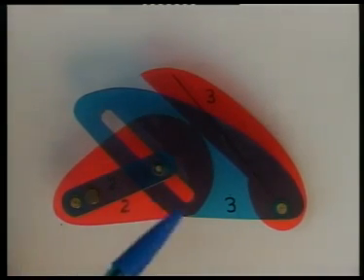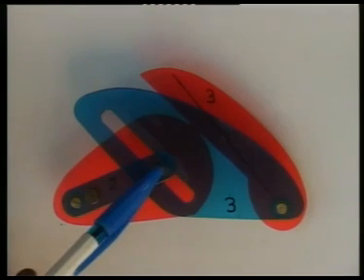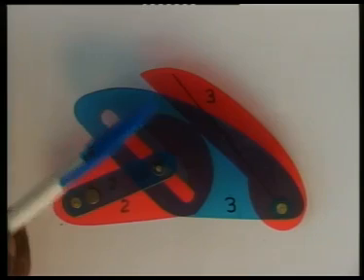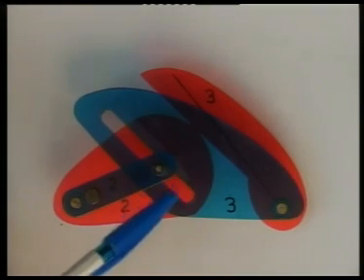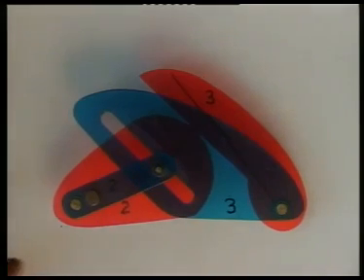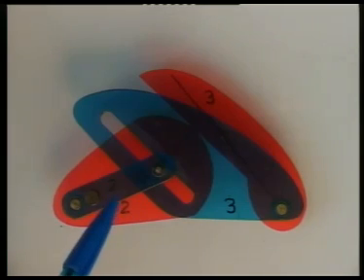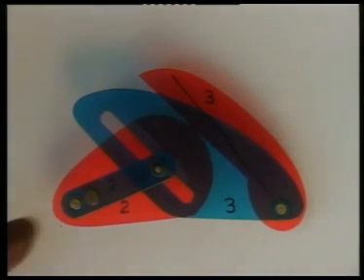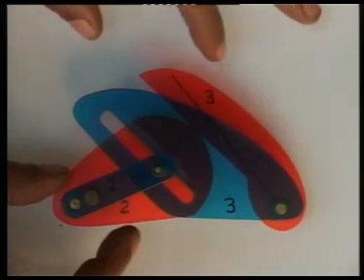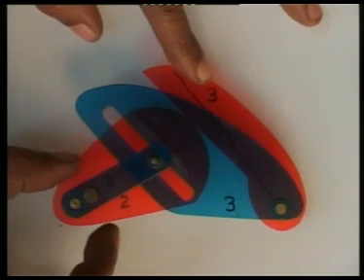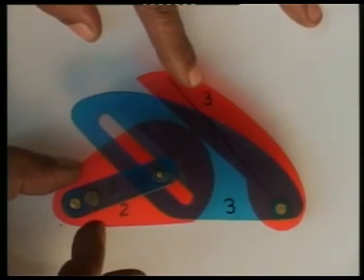Consequently, the extra link gets a prismatic pair between body 3 and that extra link, and a revolute pair between body 2 and that extra link. If we connect this lower pair linkage, link number 2, with the link number 2 of the original higher pair mechanism rigidly, then we can see that the same motion is transmitted by both the lower pair linkage and the higher pair mechanism.